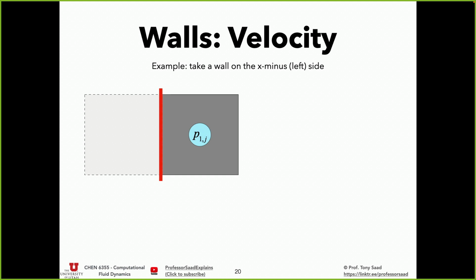Okay? So, and then we would have this fictitious ghost cell, P0J I call it. And because we're staggering to the left, we would have the same index for those velocities as this guy. In the end, what you will do, you will take that diagram that I showed you and you say, okay, what is the boundary condition here? All the velocities on that line are going to look like this. Here's the formula. Slice them or do a loop over them in Python and you're done.